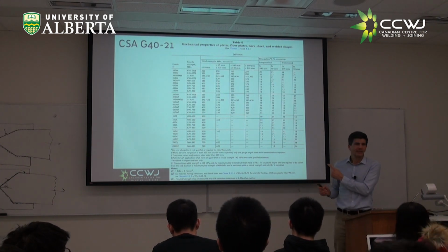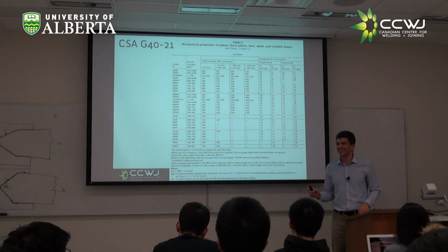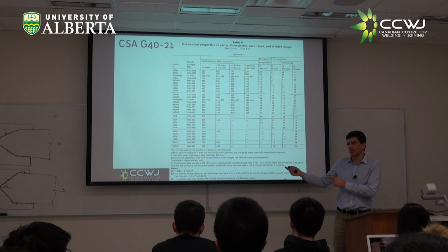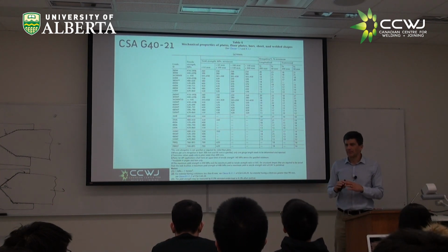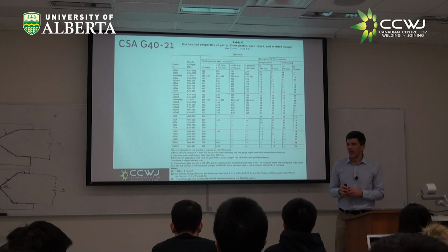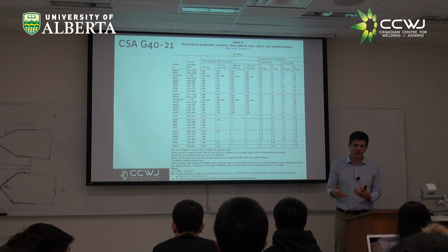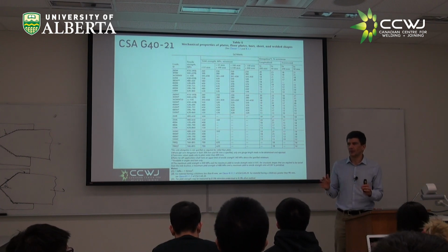So they write all this. But as you see, they never are saying, if you do it with this heat input, right? That is in their standard. But nobody says, if you're welding with a different heat input, you should change. And in this limit state that we discussed, people weld with many heat inputs and in many conditions, such that in the end, when you start changing the heat input, it's already taken into account into the limit state factor,